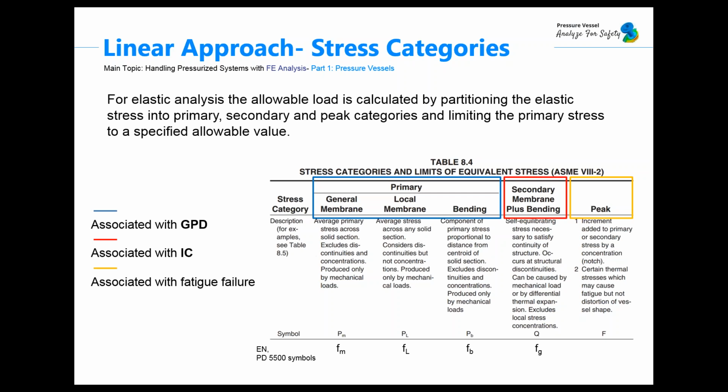So basically, primary stresses are the most critical stresses for the design, meaning that if they exceed yield stress, they will lead to failure without any doubts. They are caused by mechanical loads, and they are needed for fulfilling the laws of equilibrium, of moment, of forces and pressures.